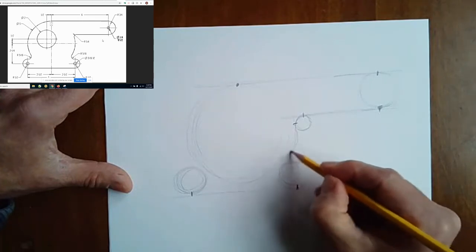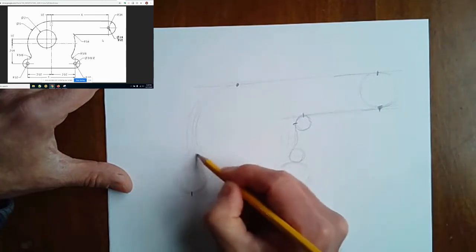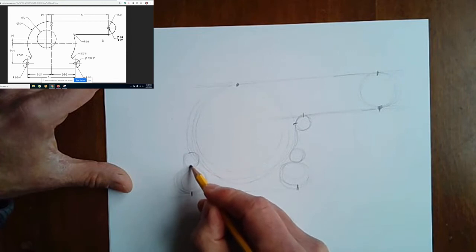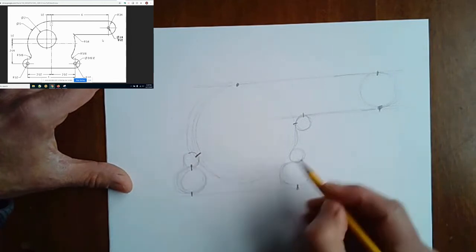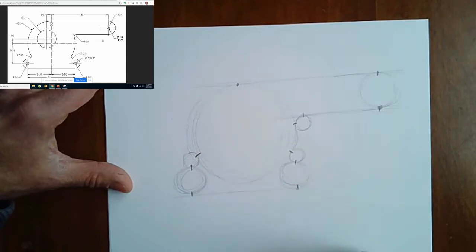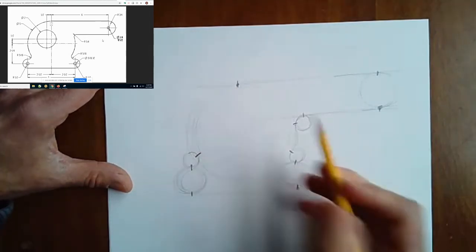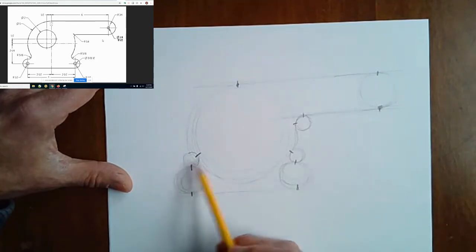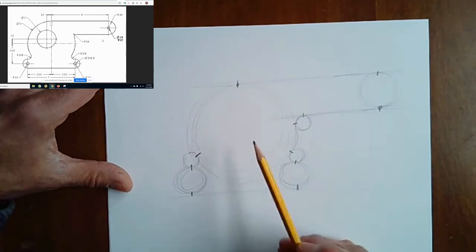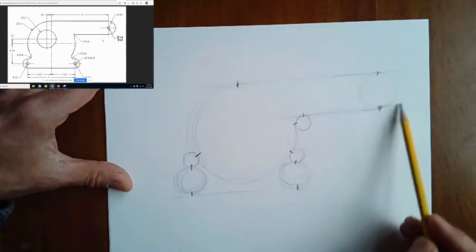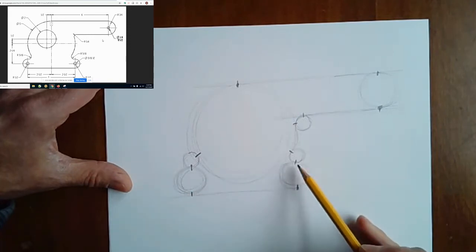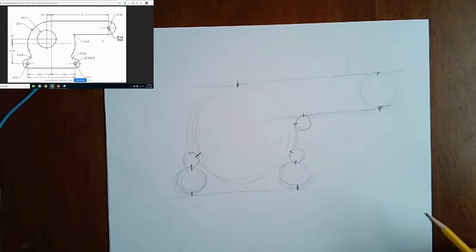So again, I'll draw that as two lightly sketched circles in such a way that it shows that it is touching those arcs at one point, only one point, so it has those tangents. So if we recall, we have 1, 2, 3, 4, 5, 6, 7, 8, 9, 10, 11 tangents, 6 of which are line to arc or arc to line. So here's arc to line 1, line to arc 2, arc to line 3, line to arc 4, this arc to this line 5, and this line to this arc 6. And the other ones are arc to arcs. So I have an arc here, here, here, here, and here. So that's 5. So that gives you a total of 11 tangent points.